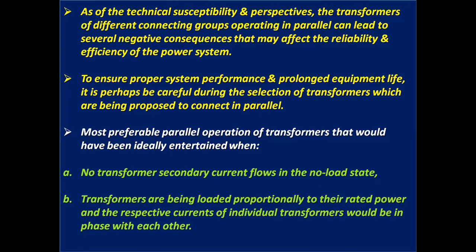The most preferable parallel operation of transformers is ideally when no transformer secondary current flows in the no load state. Transformers are loaded proportionally to their rated power, and the respective currents of individual transformers are in phase with each other.